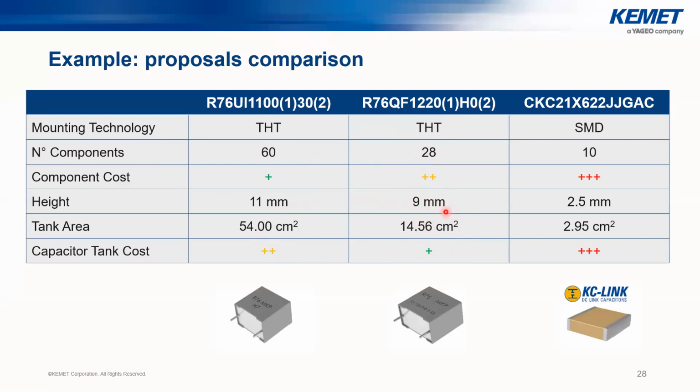And also, we will reduce the overall dimension and size of the volume occupied on the PCB. If we look at the case-sealing solution, of course, the number of components is the smallest, occupying the least surface on the PCB. However, it is the most expensive solution. But in many cases, we see that the ceramic capacitors are the chosen ones because the weight and the dimension of the overall solution is very critical for the application.